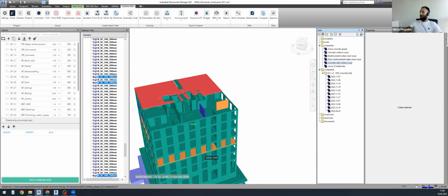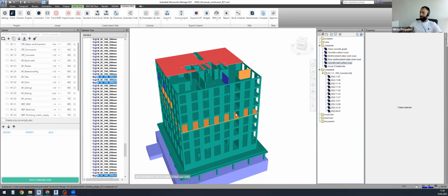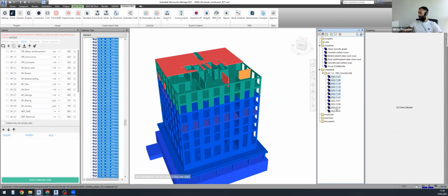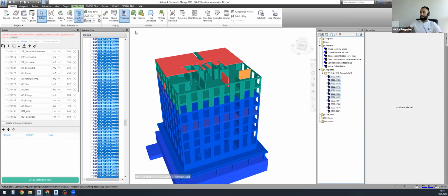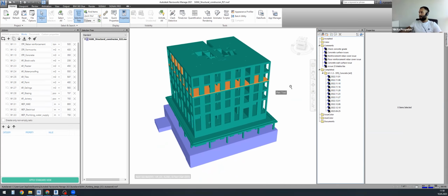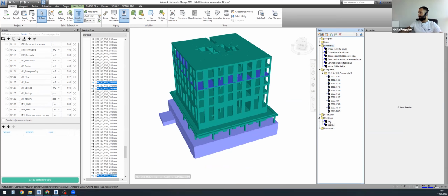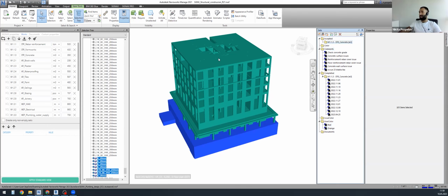Okay. So the element will be automatically recolored to red color, and the information will be stored inside the search set. So, for example, in the end of the month or some period, reporting period, we would like to get the scope of the elements that are not done with issues or with some comments. So, for example, I would like to filter November months, just hide unselected elements. And I would like to hide all the elements with the comments and issues, something like this. Hide. And I don't want to see here accepted and already paid elements.